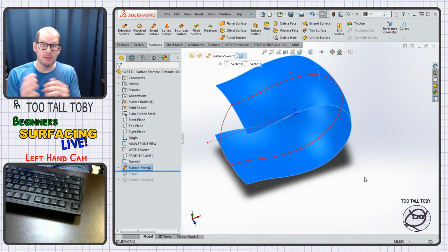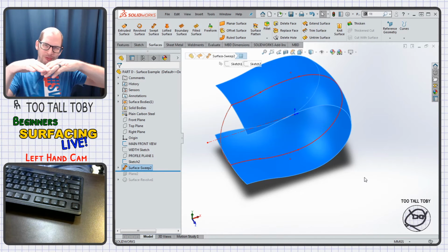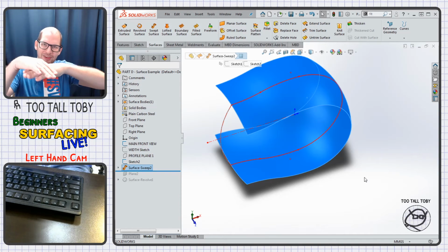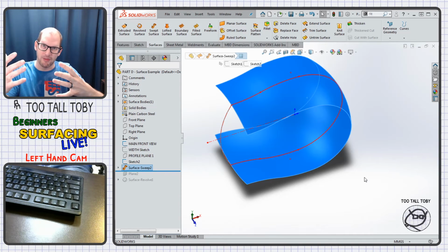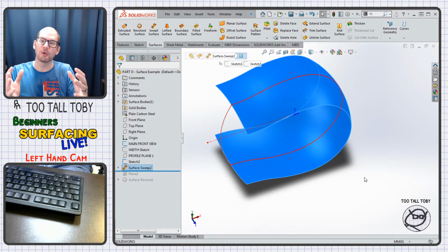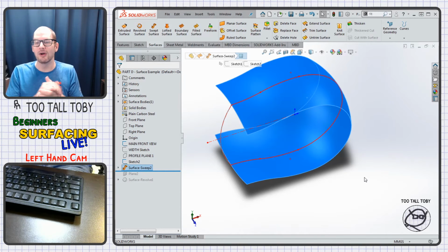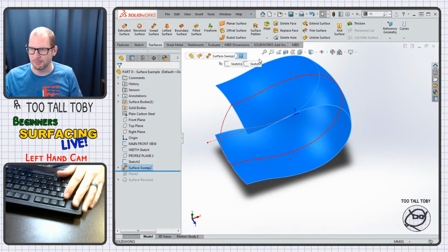Now, when you're working with a lot of surfacing and doing a lot of trimming, you don't want multiple surfaces to be coming together and creating little tiny faces. And that's what happens a lot, and that's where this is really beneficial, merging multiple faces together. It's also really useful if you're doing simulation. It's useful not to have a lot of small faces, but that's a whole different topic. So that's one example of fit spline.